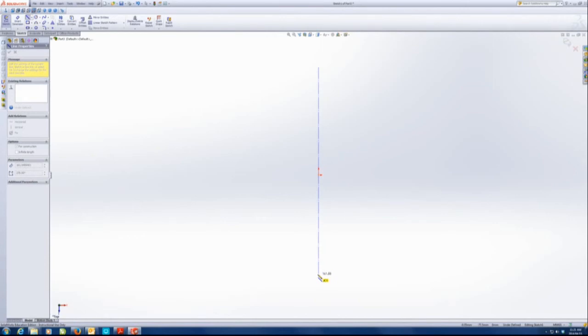You will see next to the pencil there is a yellow block with 3 lines and a green dot. That means it's bonded to the origin. And next to it is the vertical line, which means this is bonded vertically. Then we do the same on this side. Click and drag the line right through there.